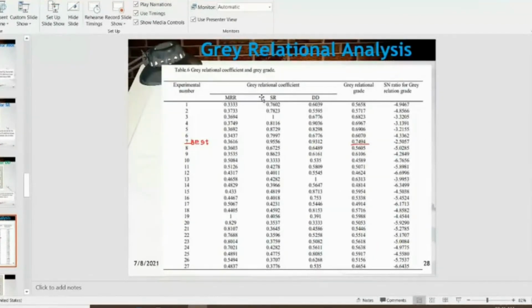So I got the gradation coefficients, and you have to calculate them for all the 27 experiments. Earlier we calculated for 9 materials, but here we have 27 experiments, because of the Taguchi method. Similarly for the surface roughness, we have 27 values, and they vary from 0.33 to a maximum of 1. When you select 0.5, the minimum value will be 0.33. If you select 0.4, it will be 0.265. If you select 0.6, it will be 0.375. Correspondingly this value will change, but the highest value will not change, right?